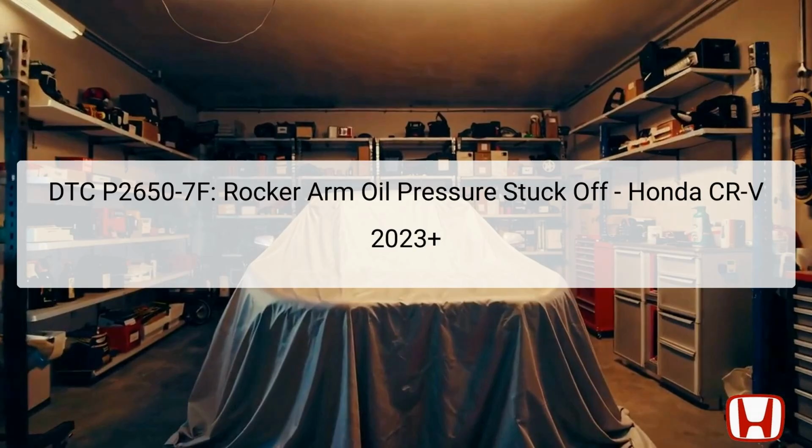The main components involved in this error are the rocker arm oil pressure sensor and the rocker arm oil control valve. The rocker arm oil pressure sensor is responsible for monitoring the oil pressure required for the rocker arm operation, ensuring that adequate pressure is available to maintain optimal engine performance. The rocker arm oil control valve regulates the flow of oil to the rocker arms, which are integral to the VTEC, variable valve timing and lift electronic control system.